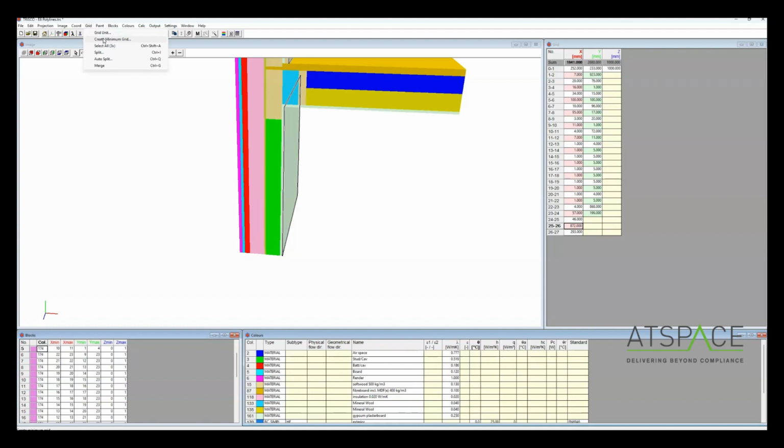But when we're actually going to run the simulation, what we need to do is have more grid spaces than that, because the simulation is going to measure the heat or the temperature at each grid reference point. So in order to get an accurate result from that and factor in the heat transfer more accurately, it's good to break down the grid into smaller pieces.